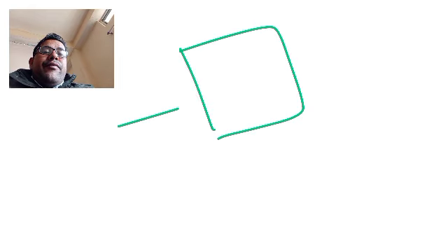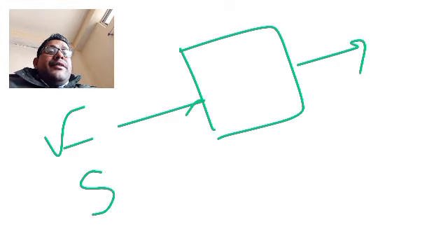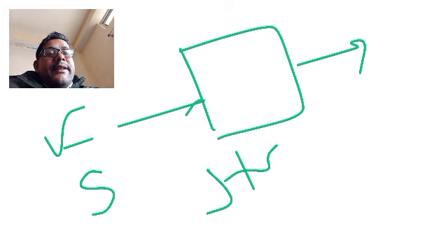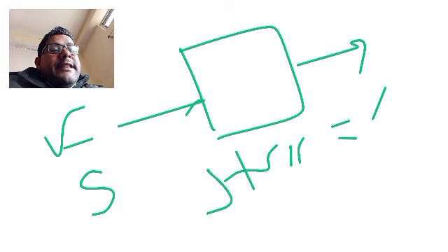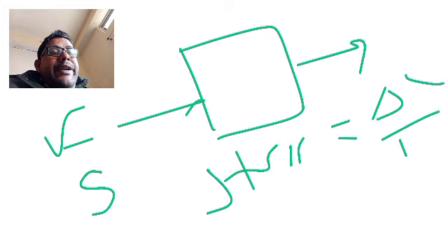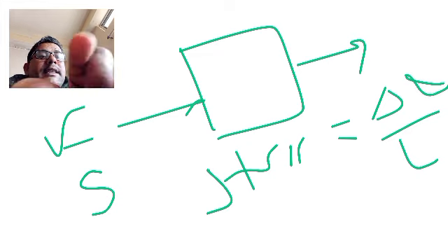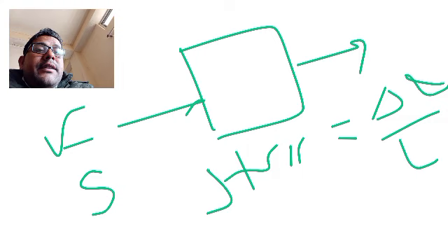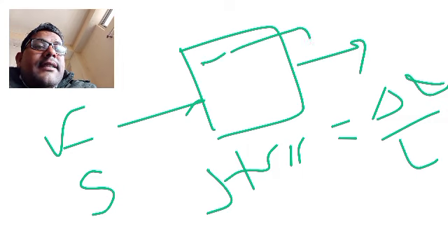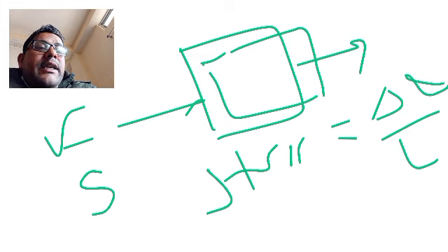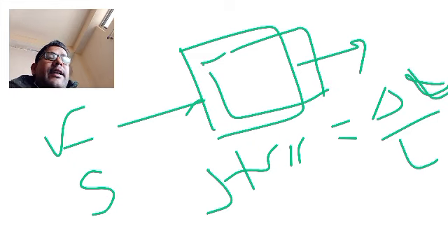So this is the strain gauge material. When force or oblique stress is applied here, it creates the voltage. What is the strain? First we should create the strain. Strain is nothing but the change in length over the original length in dimension. Suppose we apply force, its dimension looks like this. This is the new dimension, so this is the change in dimension. So delta L upon original length, this is the strain. This is the definition of strain.